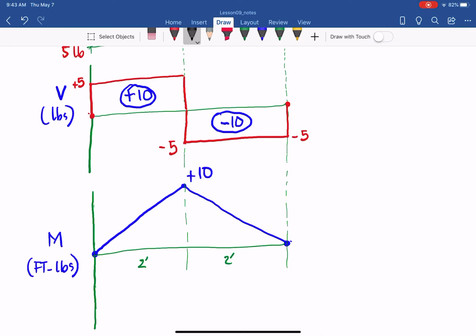Because when you draw by hand like this, we don't know if your line is really a straight line or really a parabola or cubic, etc. So for that, we need to specify whether the diagram in that portion is a straight line, parabola, or cubic. That is the maximum we have. So here, as you can see, the shear is constant, so we should specify that it is S, a straight line.